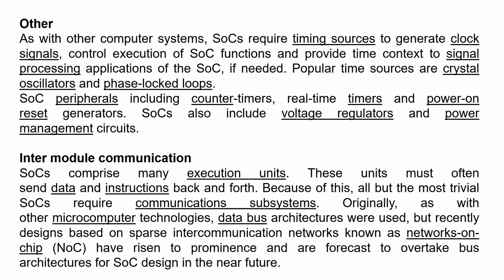Initially, for system on chips, bus based architecture was used, but with more and more integration, the number of modules present on your system on chip goes on increasing. When the number of modules goes on increasing, there can be a bottleneck with this bus architecture, and bus contention may take place, which may lead to lower performance of the system.